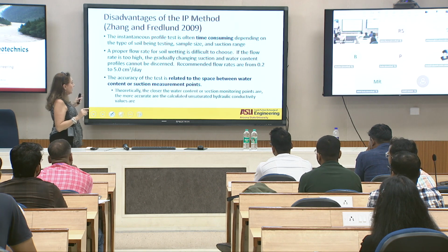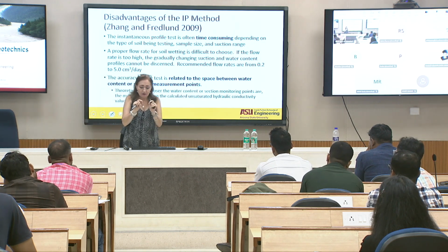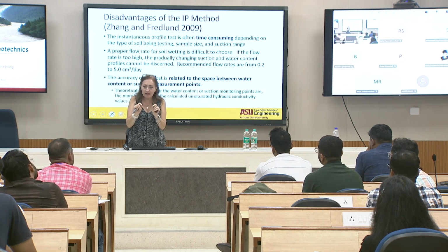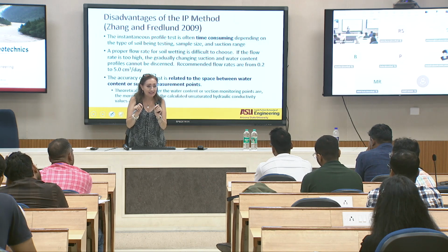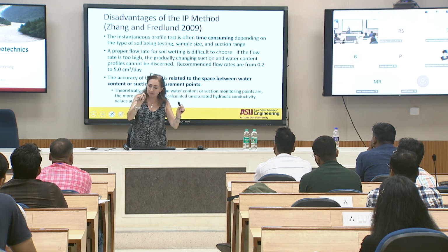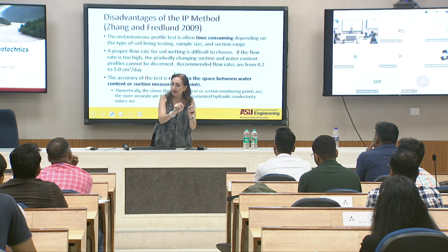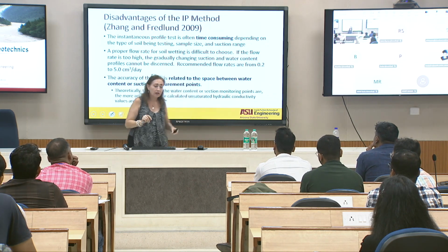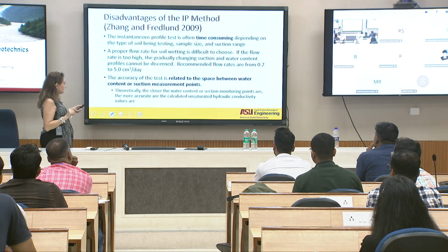And actually, the accuracy of the test is a function of the space that you have between those 2 points, right? If you have the space too high and the time too high, the water can go anywhere, right? And you can have more inaccurate results.